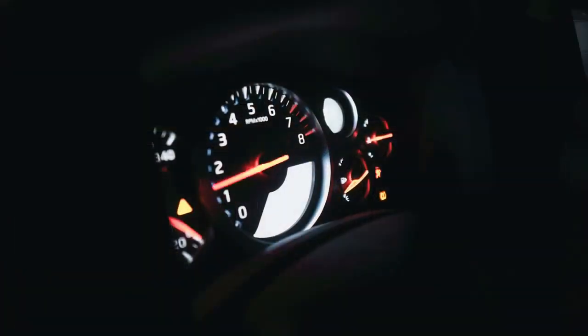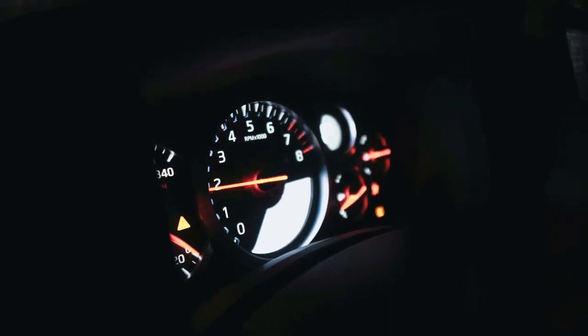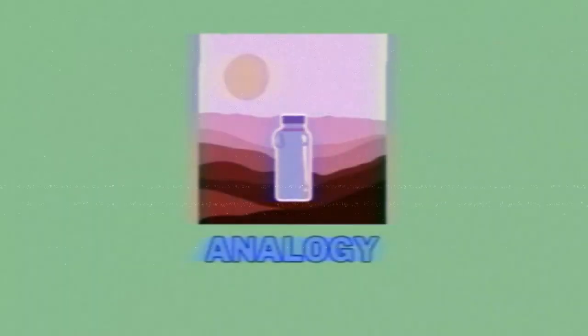So the primary purpose of a flywheel is to maintain a constant speed or provide a stable source of rotational energy in systems where the input of power or torque is not consistent. They're often used to smooth out fluctuations in energy input or output, acting as sort of an energy buffer. When excess energy is supplied, the flywheel accelerates, storing that energy in rotational motion. And when the system requires additional energy, the flywheel releases its stored energy, slowing down in the process.